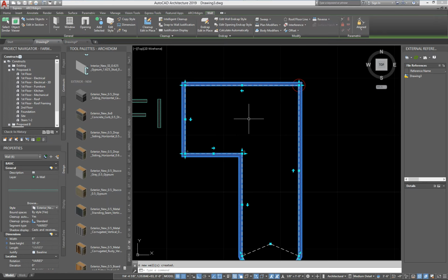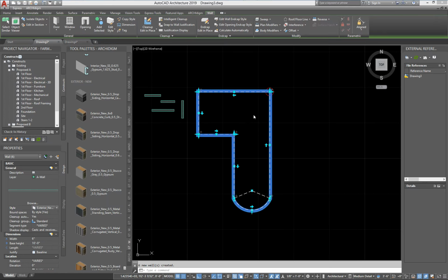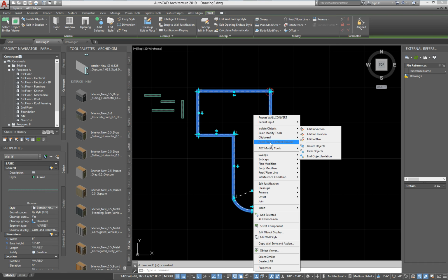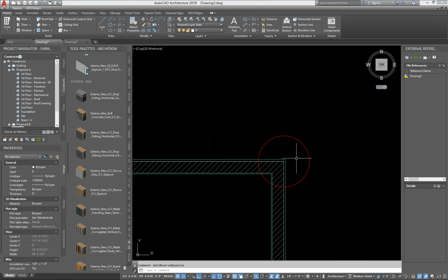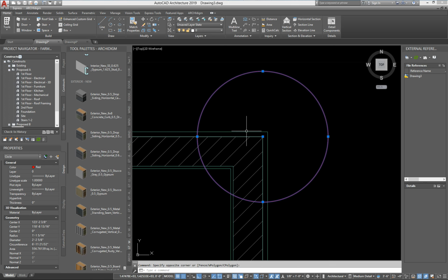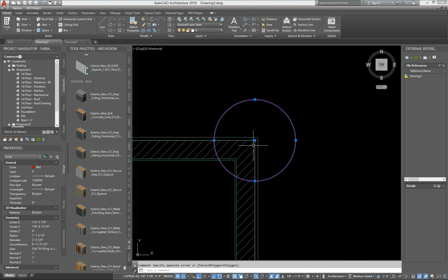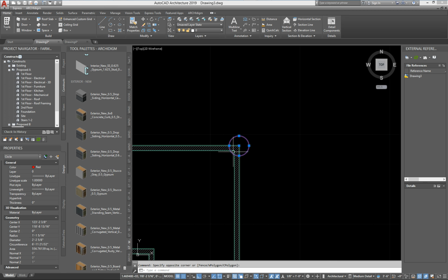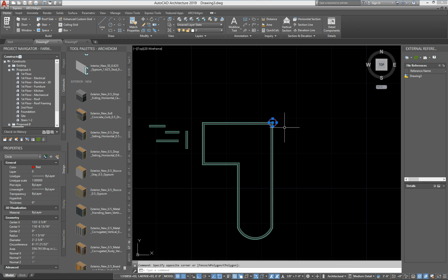properly. You could try this. You could try to right click and go down and do a reverse on the baseline and see if that helps you out. So what happened here is I select, the circle is here to let me know where the polyline is. So it used that as the outside edge. So that little trick actually worked and saved me a bunch of time.